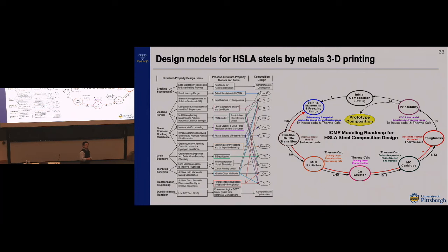So after we identify the system design chart, I believe right now people probably have better models compared with the modeling for ice cream and chocolate. Okay, so we actually identify different models from structure-property design and post-processing, including the post-processing structure-property models and tools we can identify, and most of them are linked with the CALPHAD tool. So it's not that CALPHAD alone does the calculation, but CALPHAD can provide the essential information regarding multi-component thermodynamics and diffusion. Then you can insert that into another higher-level physical model, and then you can make the prediction calculation, all right?